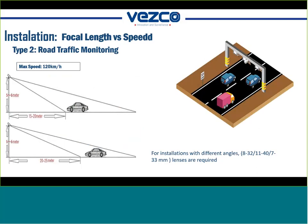Installation for our type 2, which is road traffic monitoring. So we talk here about focal length versus speed. Our maximum speed is 120 kilometers per hour. Our installation height should be anywhere around 5 to 6 meters, giving us a 15 to 20 meter read. If we're going to have larger distances, then we're going to need specific lenses. Lenses that are 8 to 32, 11 to 40, or 7 to 33 millimeters. This camera consists of standard lenses 2.8 to 12 millimeters and should give us our first scenario of a 5 to 6 meter height, a 15 to 20 meter read. In feet, that's around 45 to 60 feet.